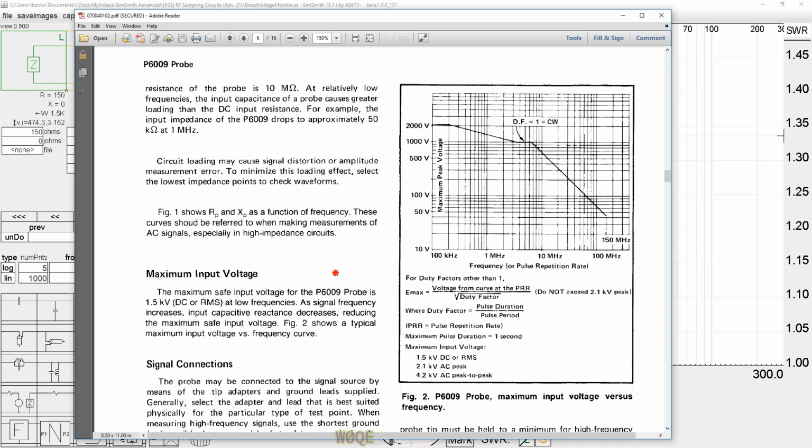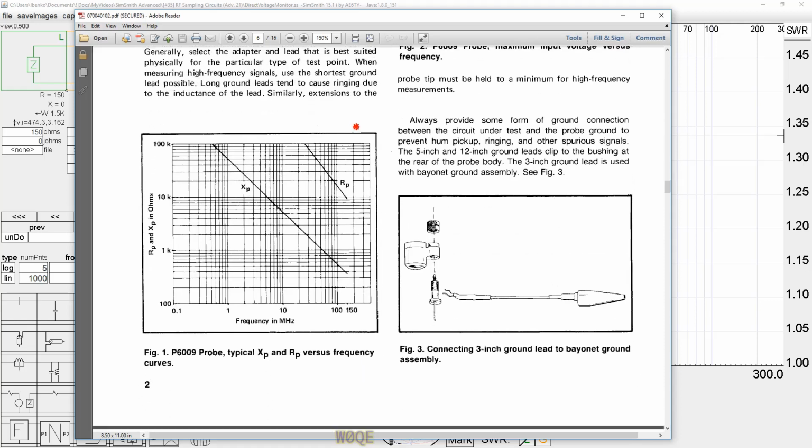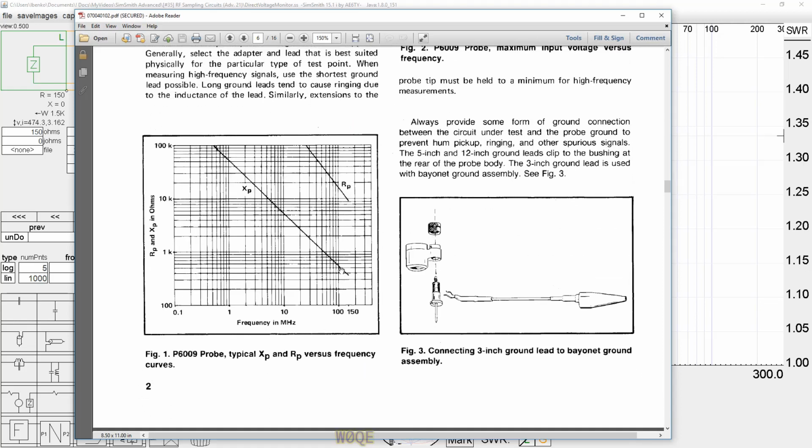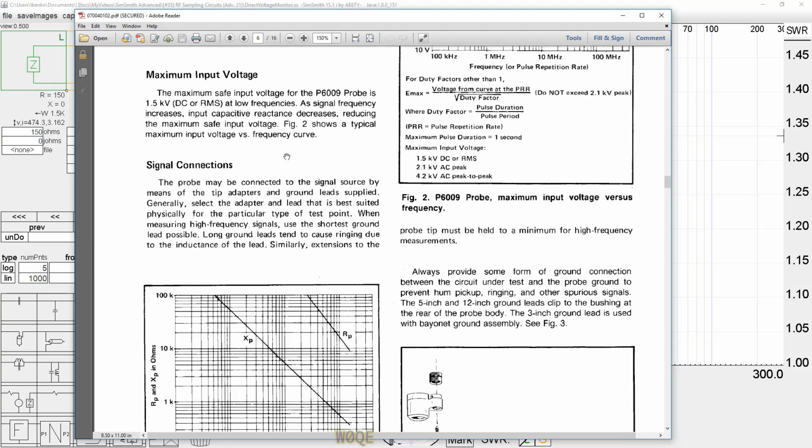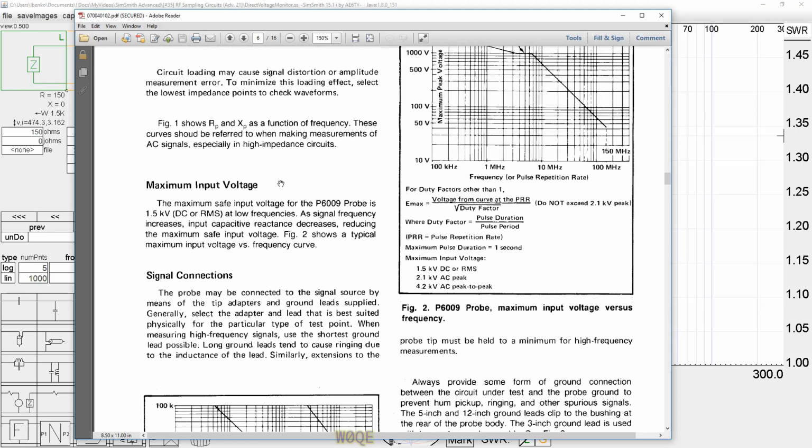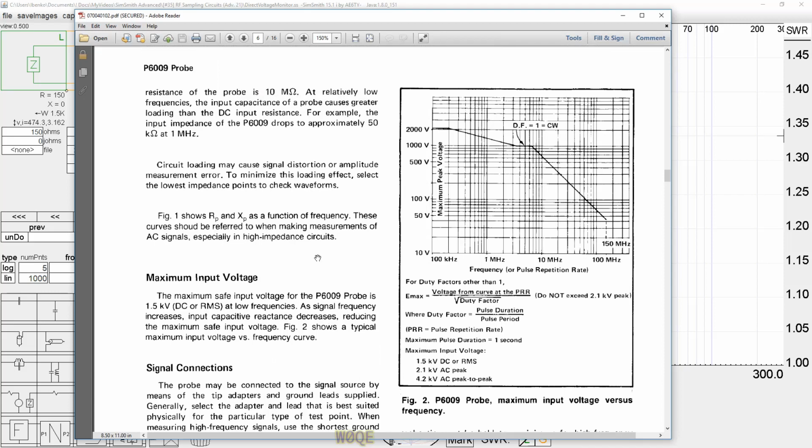Additionally, if we look at the impedance of the scope probe at 100 megahertz, we see it's about 18 kiloohms in parallel with maybe 550 ohms. 550 ohms in parallel with 18K is, ignore that, it's 550 ohms of impedance. As we saw just a moment or two ago, 550 ohms does not exceed our 1 kiloohm that we were asking for.